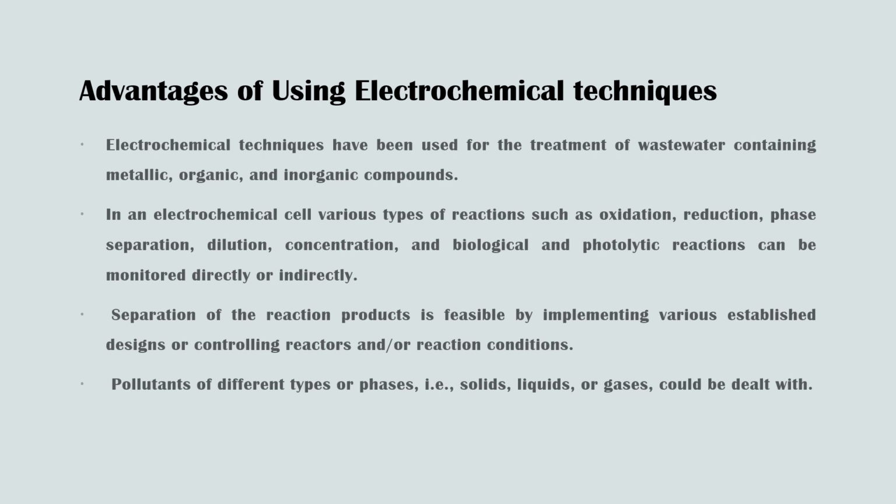These techniques have been used since the early 1960s for the treatment of wastewater containing various pollutants which are metallic in nature or organic and inorganic compounds. In an electrochemical cell, we have redox reactions and phase transfer reactions, dilution and concentration changes happening, and biological and photocatalytic reactions which can be monitored directly or indirectly.